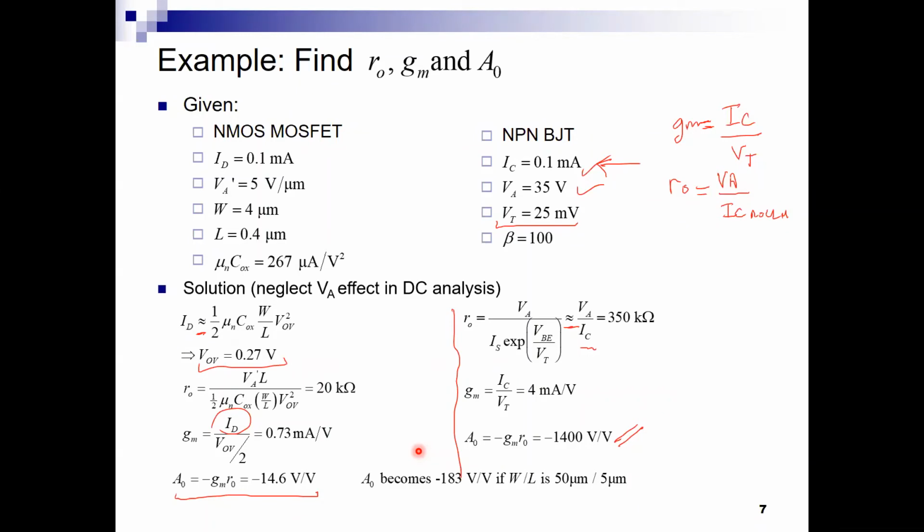what does increasing L help us? Increasing L decreases K, so it reduces the current. W and L are increasing at the same time. Let us look at it this way. Let us analyze what we are being given here. They increased both W and L. The ratio of W by L, 50/5, it remained constant, right? It's remained 10, right? 4/0.4 or 50/5, it is still 10, right?